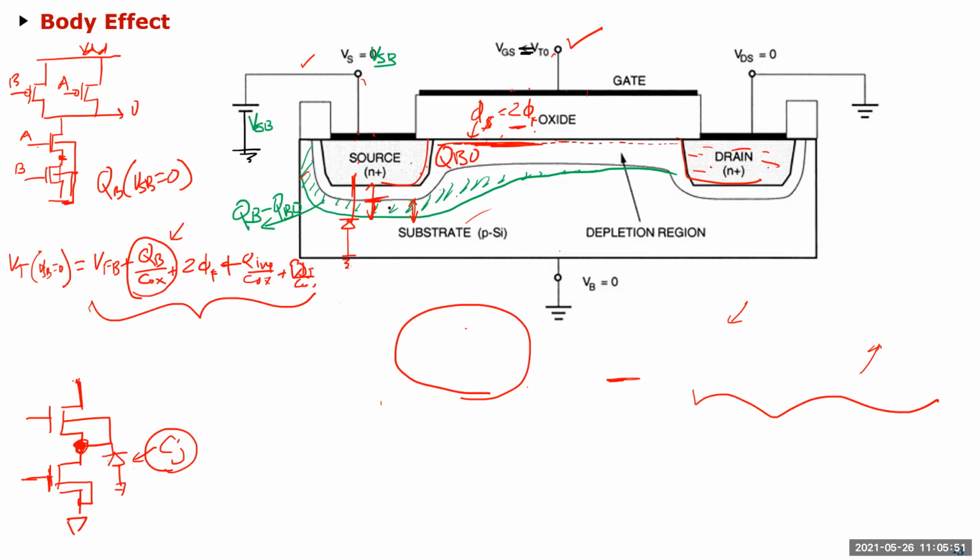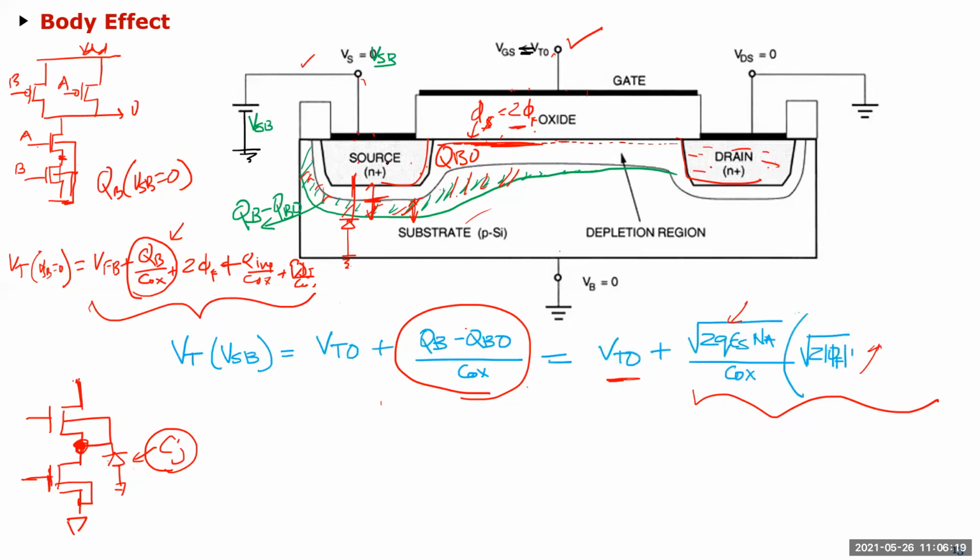But no, because this increase actually changed the surface potential, because you didn't increase it by increasing the gate voltage, you increased it by increasing the source voltage. So what you need to do now is pretend, what would be the gate voltage needed if the source voltage was 0? What would I need the gate voltage to be for it to have these extra depletion charges? And that's that extra voltage you need in the VT side. It's an approximation, but it's a pretty good approximation.